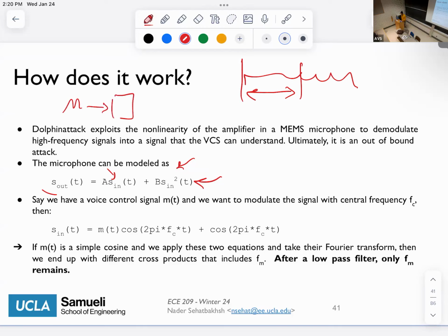And this filter, if you know a little bit about signal processing or analog design, is kind of like multiplying the signal by some form of cosine or sine function. So it's kind of moving it from a higher order to a lower order. So what will happen if you multiply a cosine to this S out? What will happen is that you will introduce new terms in frequencies.